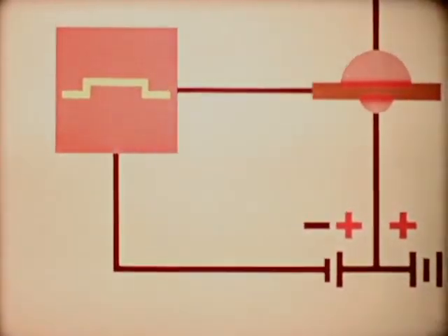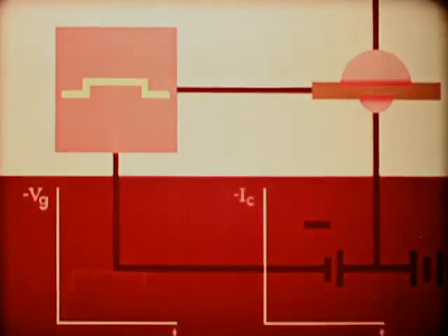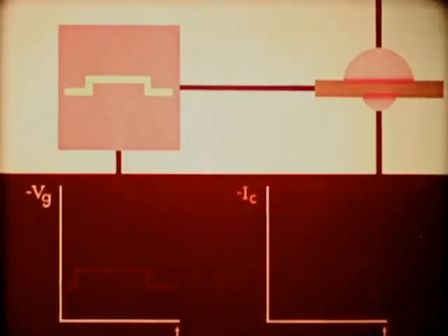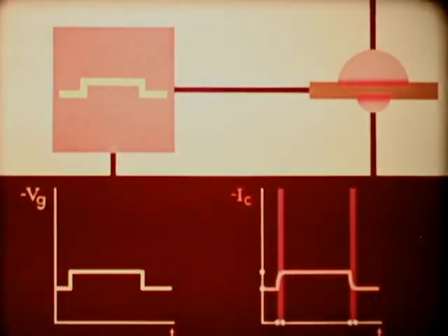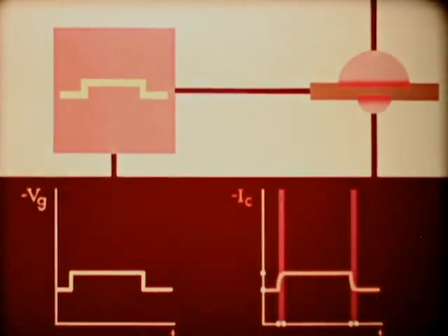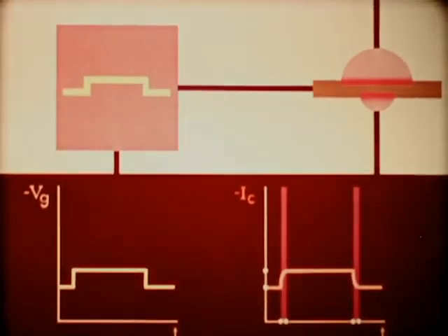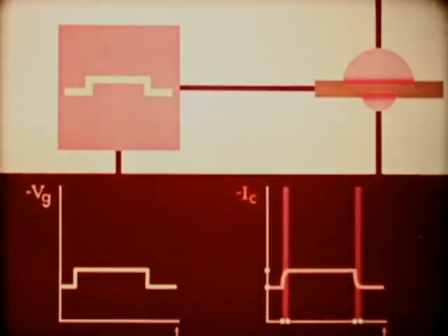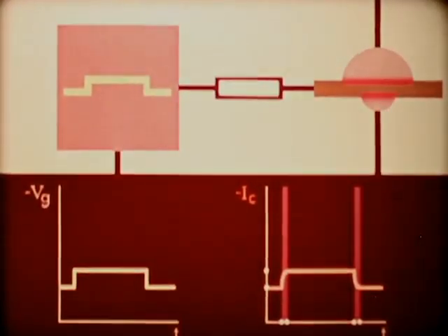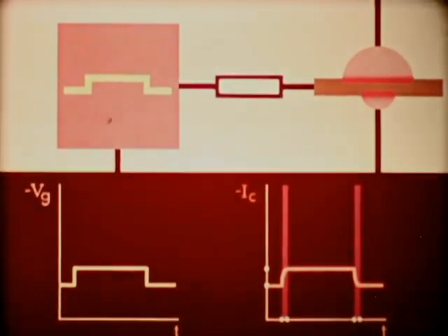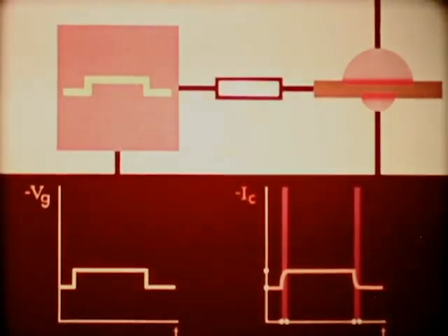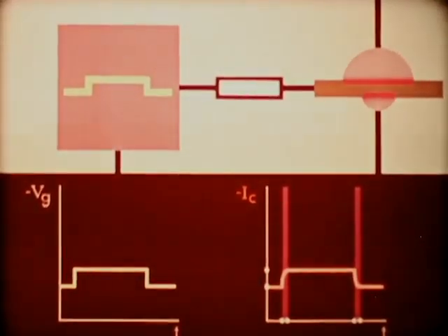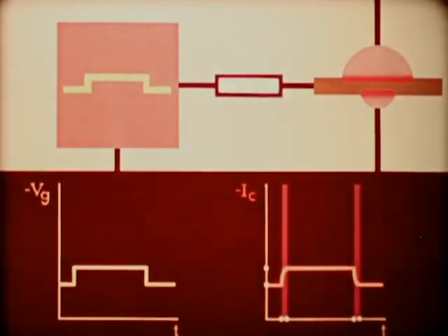So far, we have studied the effect resulting from the direct application of a stepped voltage pulse. This technique, known as voltage steering, may, however, lead to very high input currents. In practical circuits, therefore, this input current will always be limited by an input resistor. Because of this limitation on the value of the input current, it is said that the transistor is current controlled.